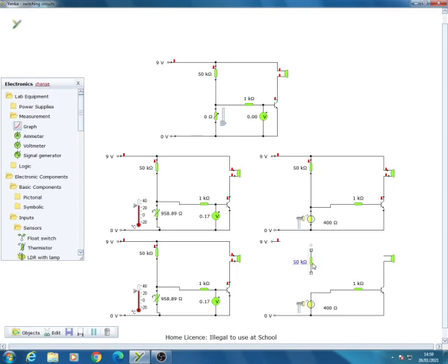I'm going to get my 50k resistor and my light dependent resistor, and I'm going to put the light dependent resistor on the top now, and put the large resistor down here at the bottom, connect it up like this, and you can see it's light and the buzzer is on, and as it gets darker the buzzer switches off. So what I've done by swapping these two over is reverse what happens.